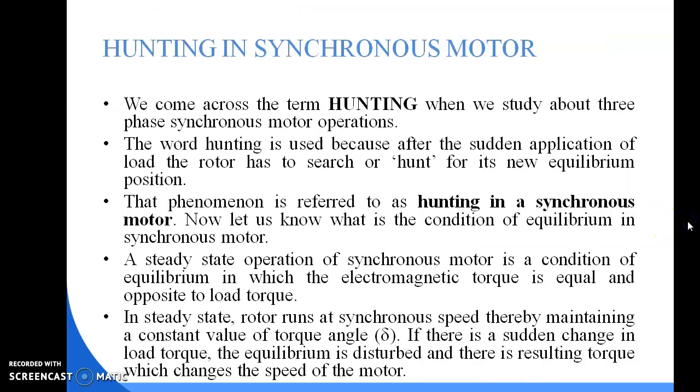So now we will discuss another important concept in synchronous motor, that is hunting. We come across the term hunting when we study three-phase synchronous motor operations. The word hunting is used because after the sudden application of load, the rotor has to search or hunt for its new equilibrium position. That phenomenon is referred to as hunting in a synchronous motor.